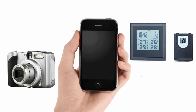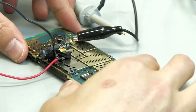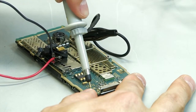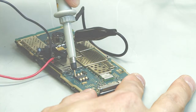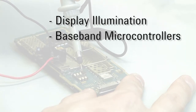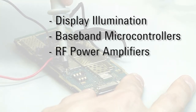Users of mobile phones and other wireless devices are always looking for longer battery life. Measuring your mobile device's overall power consumption is useful for optimizing battery runtime, but you also need to measure and analyze your device's subcircuits. Some examples of important subcircuits include display illumination power controls, baseband microcontrollers for voltage frequency scaling, and RF power amplifiers when dynamic voltage control is used.